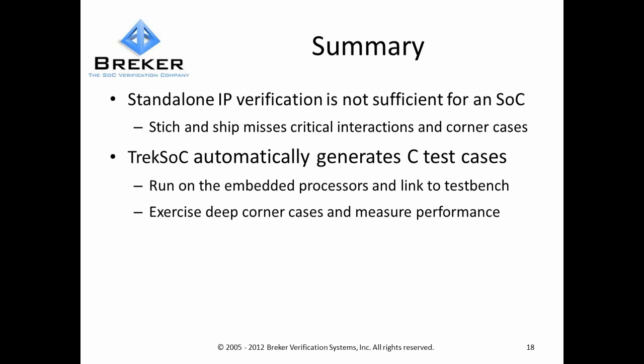Trek SoC was designed specifically to go after this test case. It uses these graph-based models as inputs, and that input drives a scheduler that knows 80% of what there is to know about verifying the system in general. You can generalize the problem of SoC verification if you say SoC verification is about moving data, and we can build a tool that automates concurrent producer-consumer data chains through a system. Now all we need is to know what are the rational data flows through a system, and what are the steps we need to do for each IP to get them to move the data.